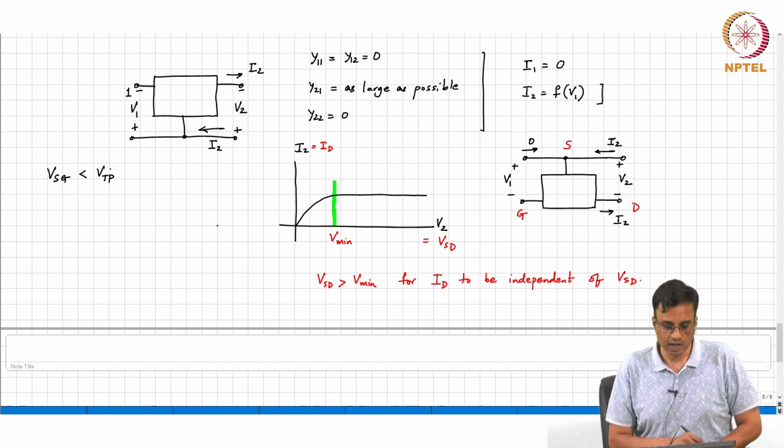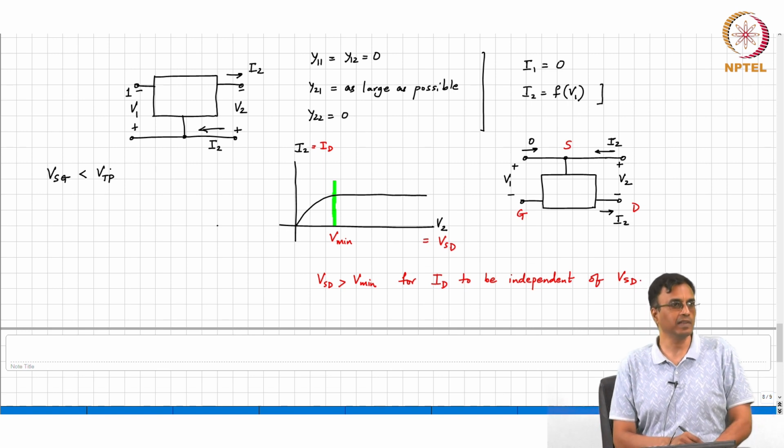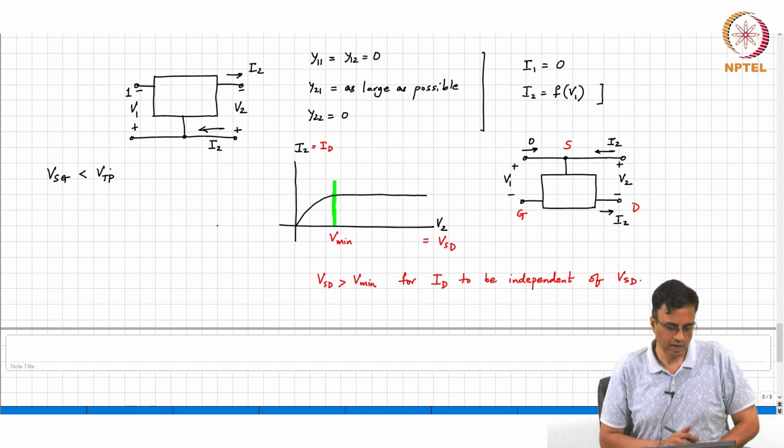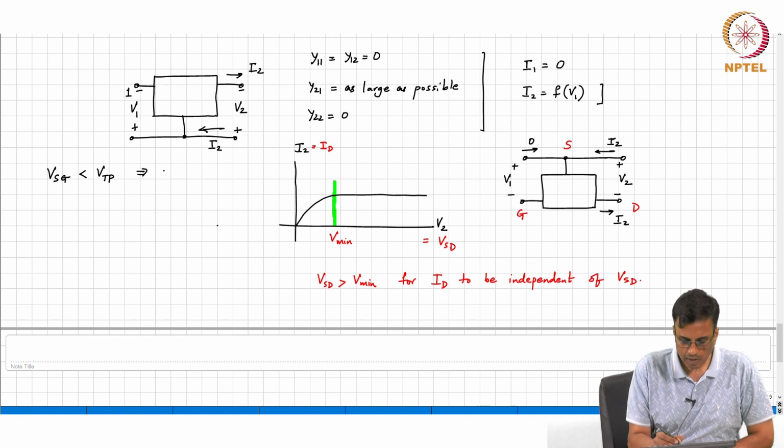Now we have two kinds of devices. The earlier devices were called the NMOS transistors, and their threshold was VT. Since we now have a PMOS transistor, to distinguish the thresholds of the two devices, you have a new subscript. VTP represents the threshold voltage of a PMOS device, whereas VTN denotes the threshold of an NMOS device. So, if VSG is less than VTP, the transistor is off.